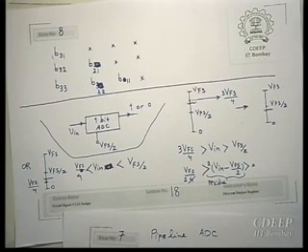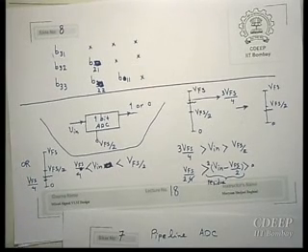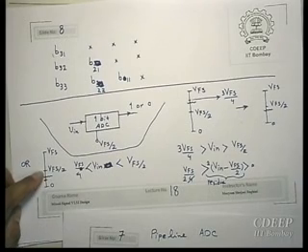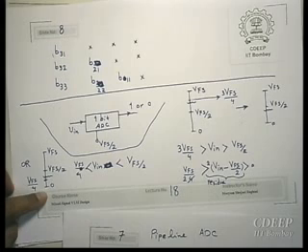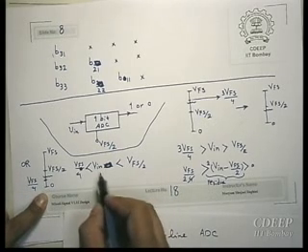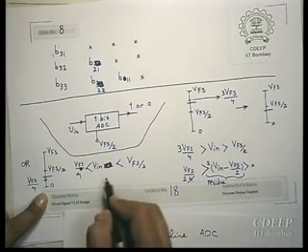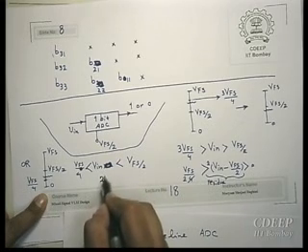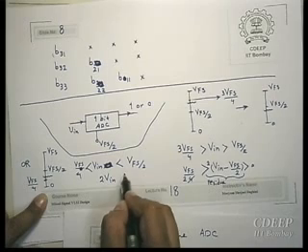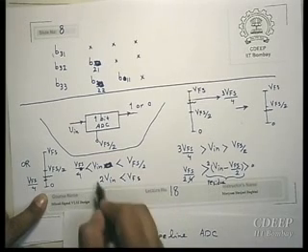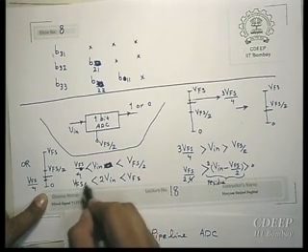The closest level is 0. Therefore, I will just make V in minus 0 and multiply by 2. Therefore, now 2 V in will be less than V full scale and greater than V full scale by 2.